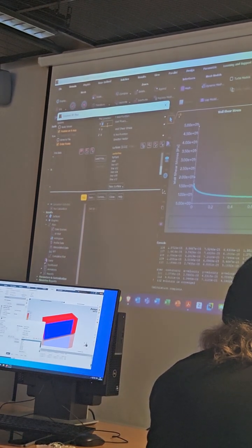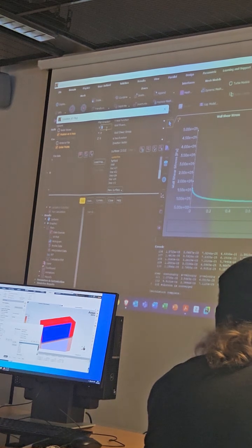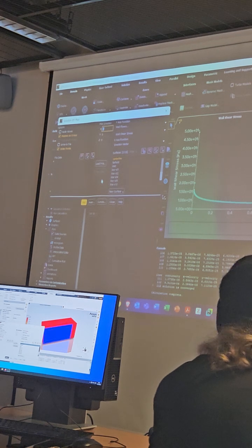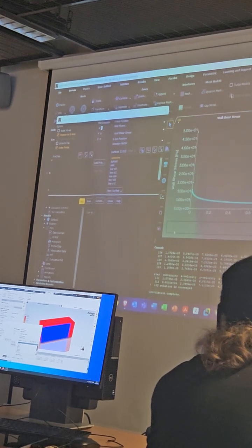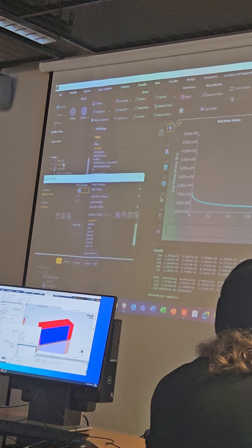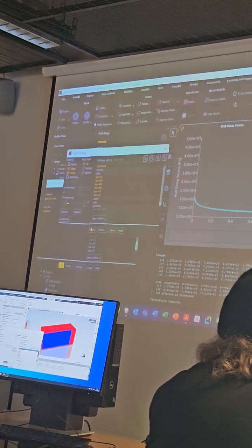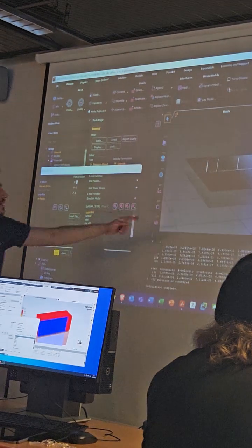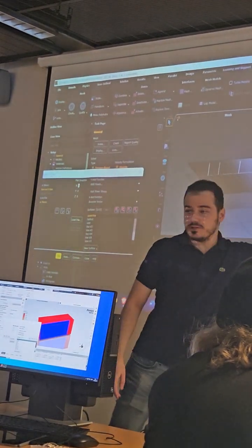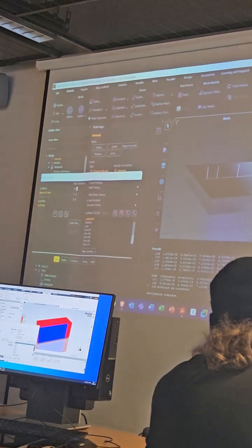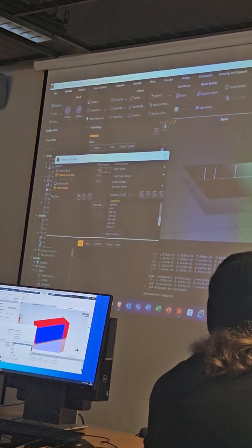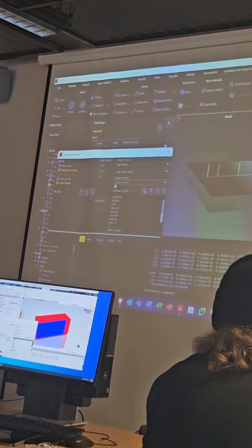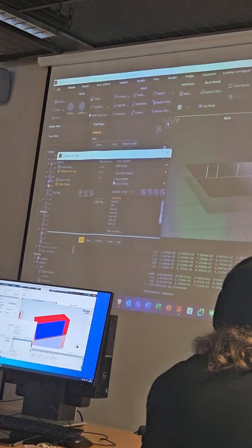You know that these lines are in the direction perpendicular to the plate, that we call y in the geometry. But if I'm showing this, you can see that these lines over here in Fluent are in the z direction. So we need to set our plot direction to x0, y0, z1. That means you want to plot the variables along the z-axis.